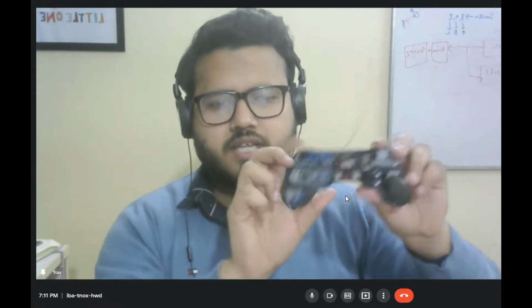So you can control the direction of our robot by the joystick. There is one another sensor. This particular sensor over here is called a gesture sensor, or technically it is called an accelerometer. This sensor detects the tilt, or the changes in the orientation of this sensor, and it generates an analog value with respect to that. So let us say if my remote is like this, and if I tilt this in the right or the left direction, or in the forward or backward direction, this gesture sensor or accelerometer sensor will give us some changes in its x, y, and z coordinate values.